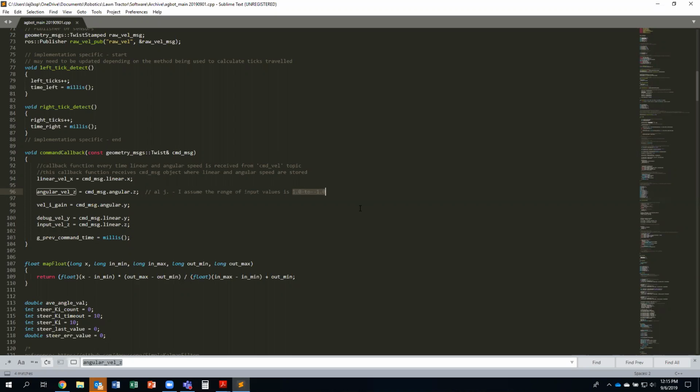So it's based on whatever the limits are set at in ROS. Well, actually, no, because if you're treating that as a steering angle as opposed to a rotational velocity, then I guess that doesn't apply what I just said. Since the TEB planner is substituting that for something else, it's not in radians per second. So I don't know what his limits were on that.